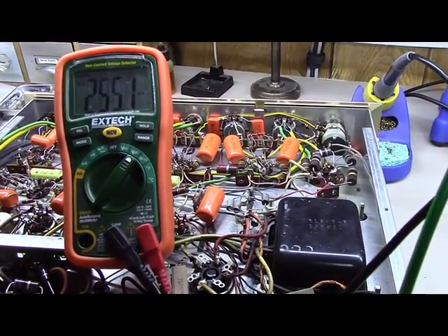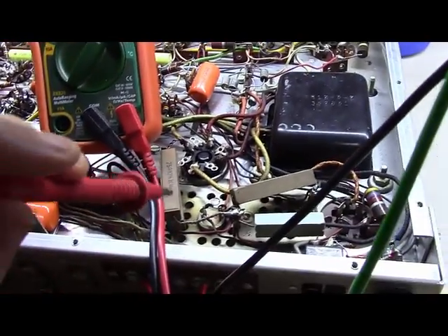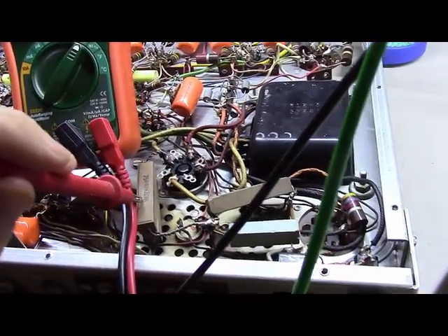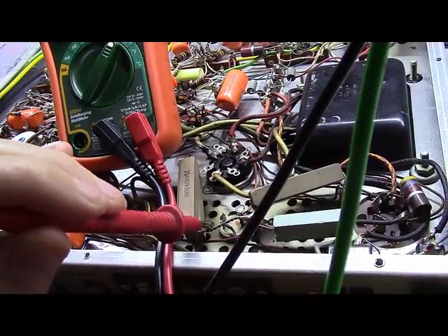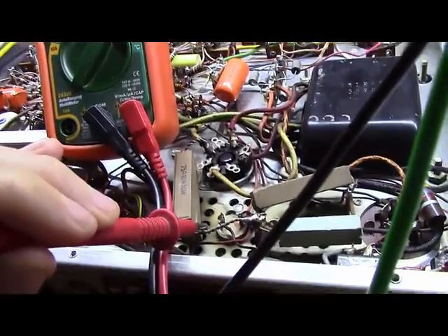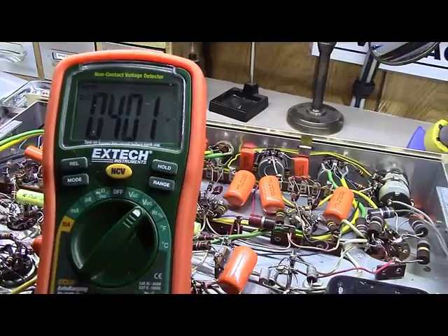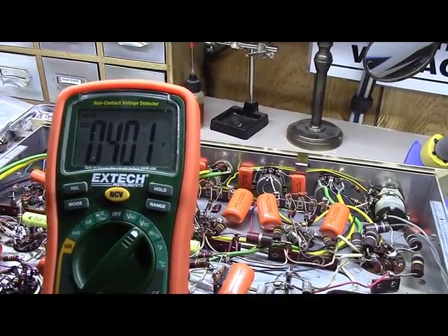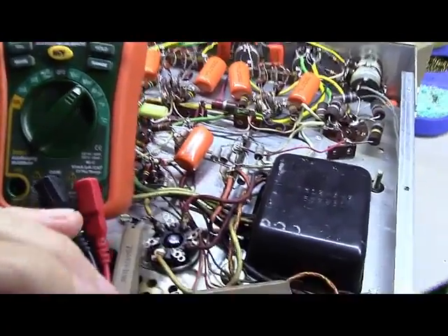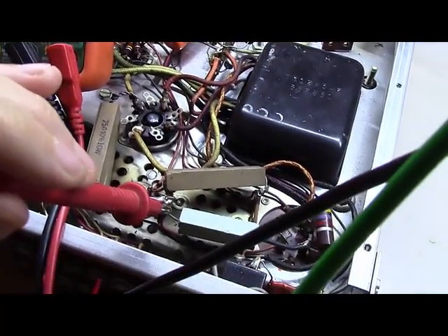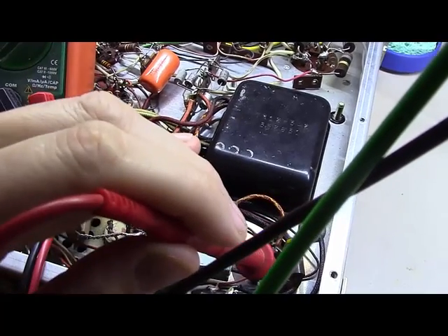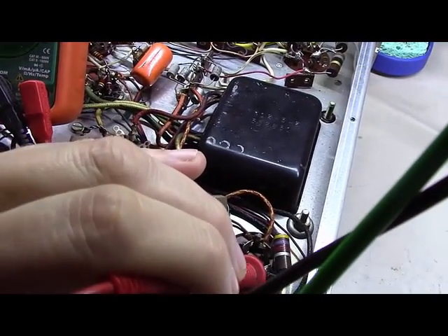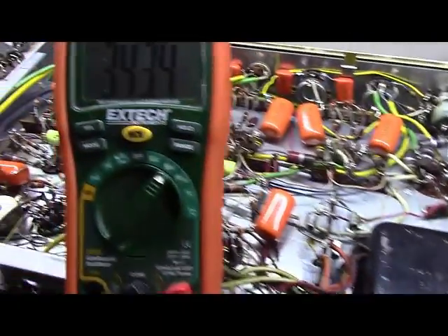If you'll notice, there was a resistor that was in there to drop. Well, there's a set of resistors right here, and they're in parallel, and they actually are about 60 ohms total when you put them together. And if you'll notice, if I touch the other side of this thing, I just went from 410 volts down to 401 volts. Well, if I come on the other side here of that resistor, there's another resistor here, and it drops it down here to this point. And if I touch that point, look at this. I'm down to 343 volts.